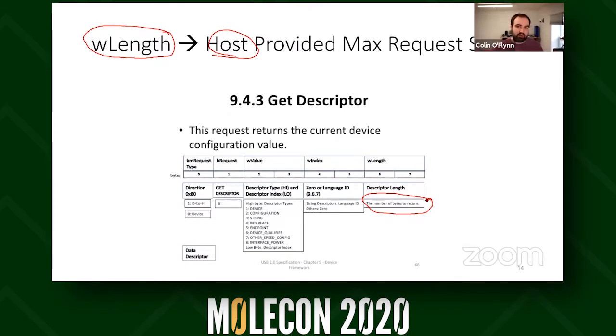And the idea is the computer can request, at the beginning, you don't want a bad USB device that has these massive strings to, I guess, waste the time. And the USB spec was designed quite a while ago when there were concerns over memory usage and the initial speed was pretty slow. So you had some stuff like that, right? That the host is only going to ask for maybe the first little bit of the descriptor to figure out if it even wants to request the rest of it, right? So it can request the first 16 bytes and later request everything if it decides, yes, okay, I need the full string. I need the full serial number.